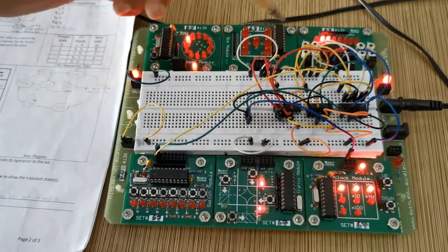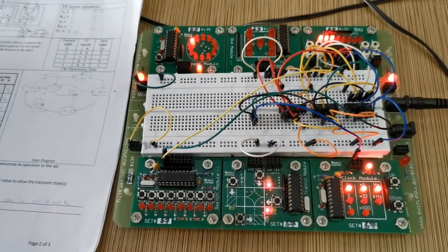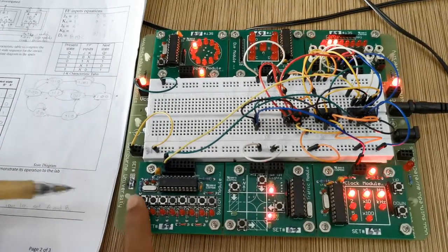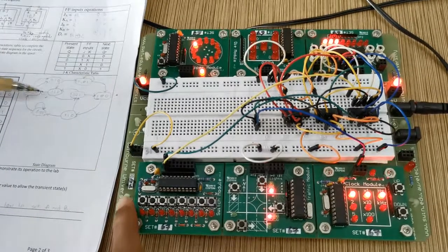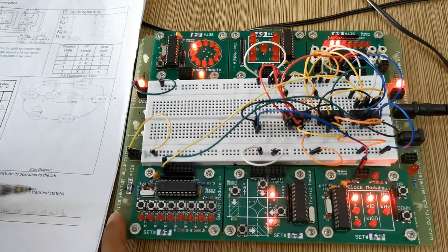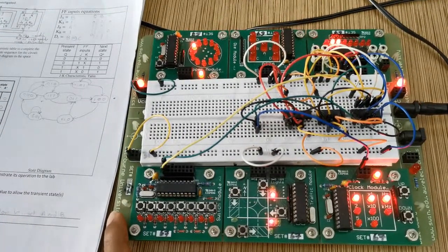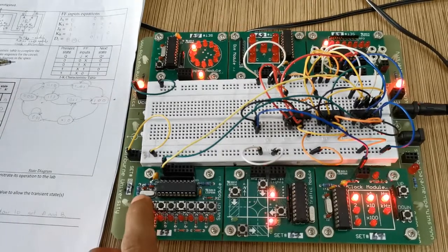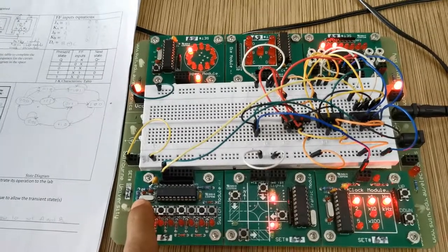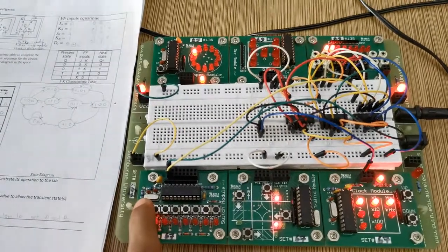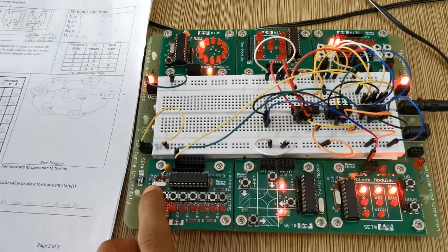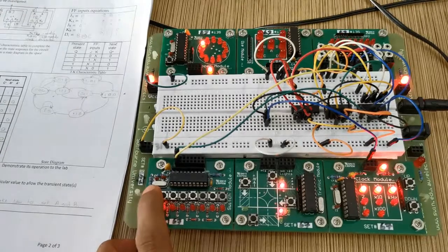As you can see from these, the light output follows the inner diagram, considering that both the switches Ka and Kb are giving a value of 0. So over here it rotates between 111 and 011. However, if both these switches were to give a value of 1, then we would enter the outer loop. So the outer loop is 100, 110, 001, 000, 010, 101, 100, and so on. It would just keep in that outer loop. And once we give them a value of 0, we'll enter back into that inner loop.